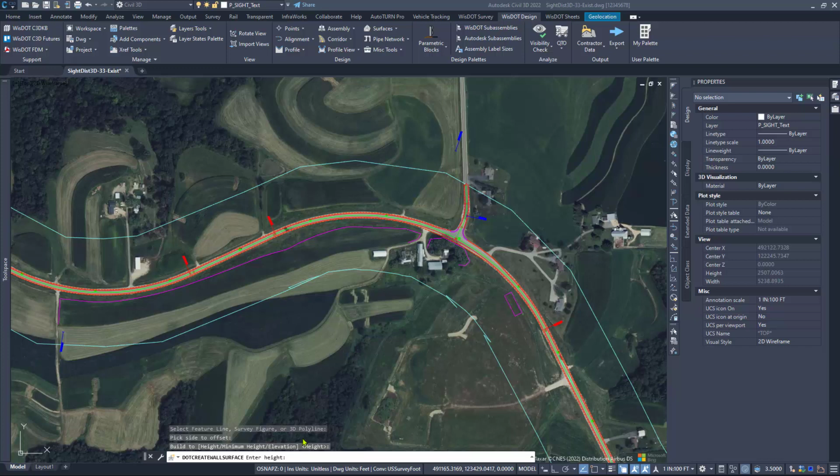For this, I'm going to say it's a cornfield, so let's just say we'll give it a height of 16 feet. Enter the name for the wall surface. I like to use something that describes that feature and then also the relative location of that just to stay organized. So I'll just say this is crops and then the stationing and then it's on the right hand side. And then that creates that wall surface.